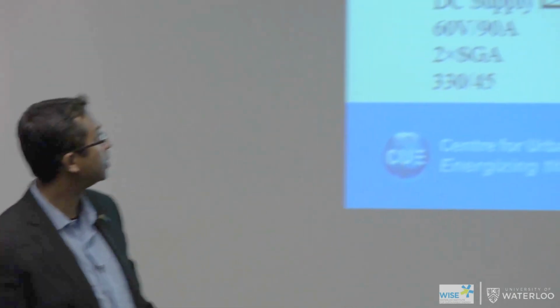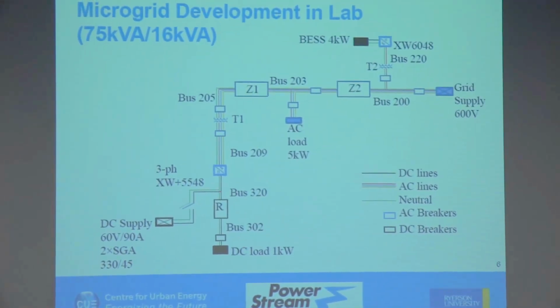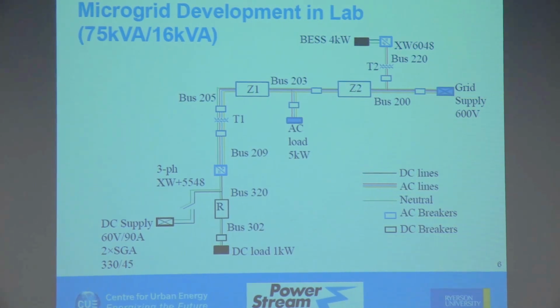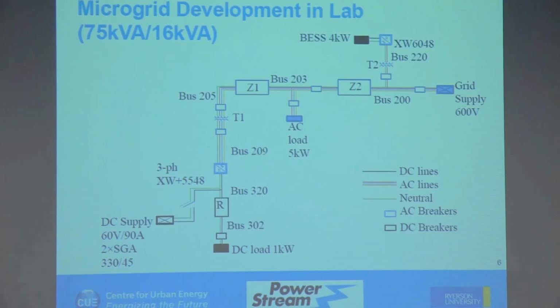What I could also do is translate this to a PV, and if that PV is about 10% of the total DC supply in terms of power, I could still have that generator as a slack bus, as long as the output after the solution is within the range of that generator. If the solution tells me that the output of that generator is more than its capacity, then it's infeasible. So basically, when we solve power flow, the output decided by the algorithm should be within the generator's capacity. That's the only constraint. Whether it's strong or weak doesn't make a difference.